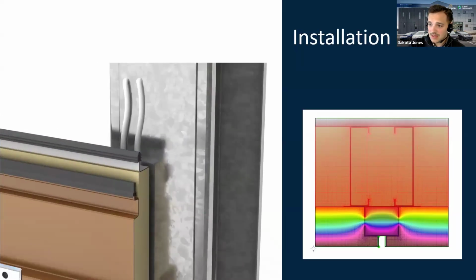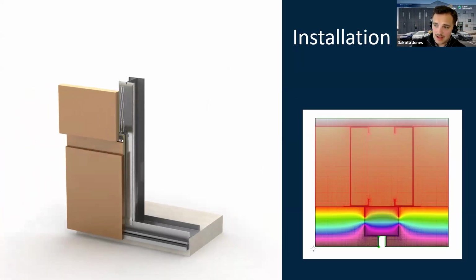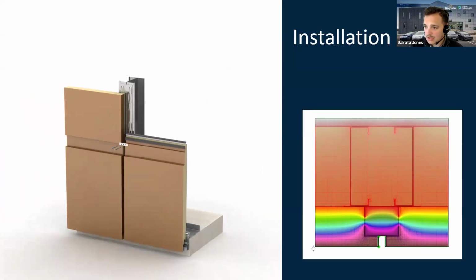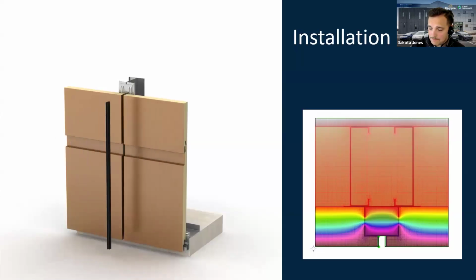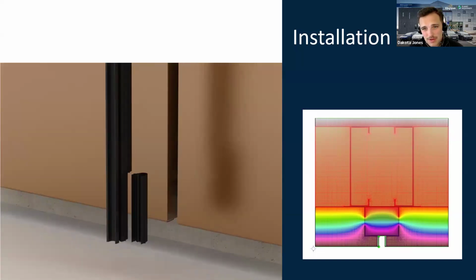Now, we saw the two lines of that sealant, that butyl, go on, and then the IMP put on top of that structure. This is attached directly onto the studs. It's then fastened via a clip, and then you just saw two lines of that non-skinning butyl going over that back gasket. The reason for that is to keep the system from being compromised laterally as far as water infiltration. Very important step. We call that a marriage bead. It'll be shown just in a second again as the next IMP goes on into its right. The IMP goes on there, it's glued, double fastened, we saw that marriage bead again, and the next IMP goes on top. And then, of course, we have this pressure-fitted gasket, which is going to keep water infiltration from occurring.